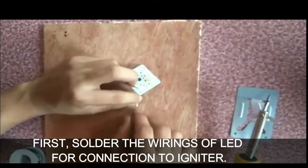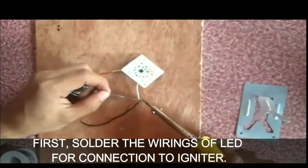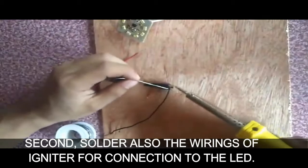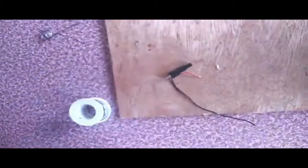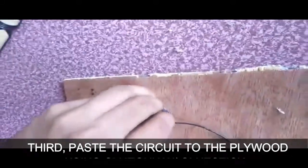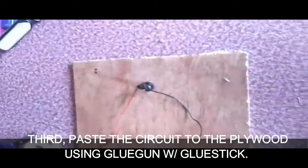First, solder the wirings of the LED for connection to the igniter. Second, solder also the wirings of the igniter for connection to the LED. Third, paste the circuit to the plywood using a glue gun with glue stick.